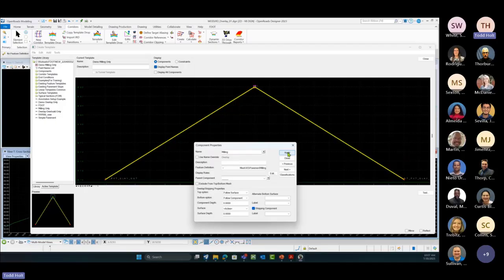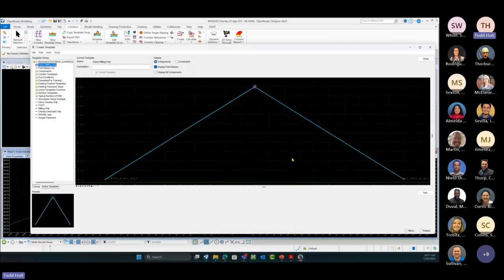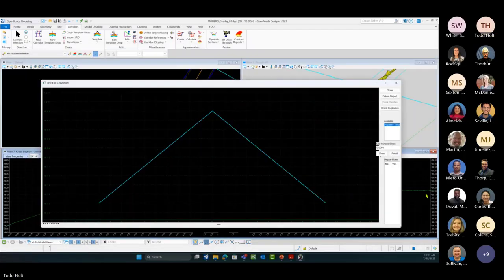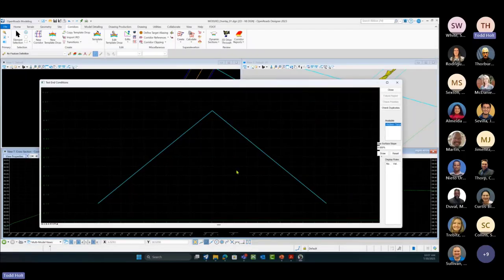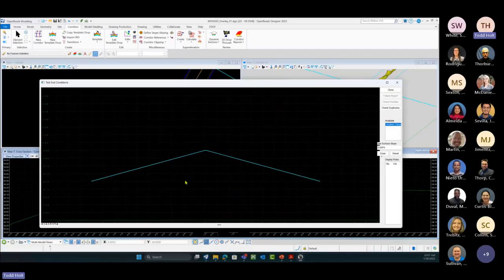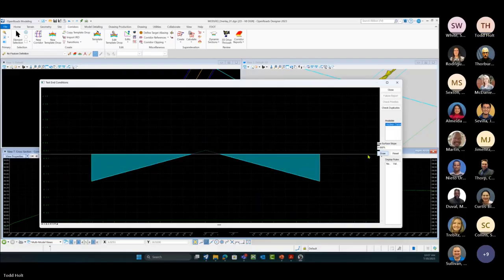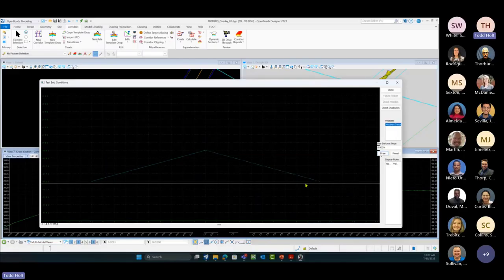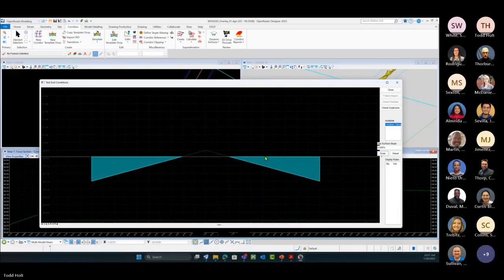So there we've created our milling. We did change the feature definition to milling. So we're going to click apply and then close, and we'll test our simple milling component. Right, so I'm just going to do our zoom to get that in so we can draw at 0%. Right, so if our existing ground is below the bottom of our component, we're going to draw down.